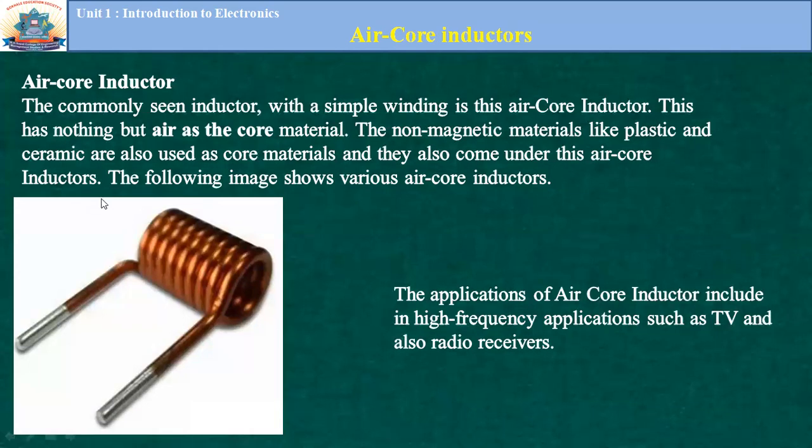This is a very commonly used inductor, and it is a simple winding with nothing but air inside. Non-magnetic materials like plastic and ceramic are also used as cores. These are used in high frequency applications where you have to generate high frequency signals.